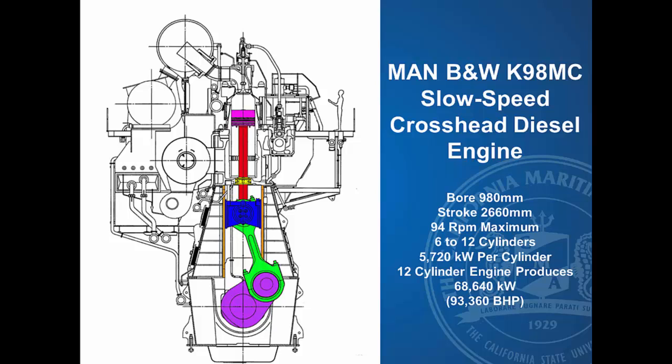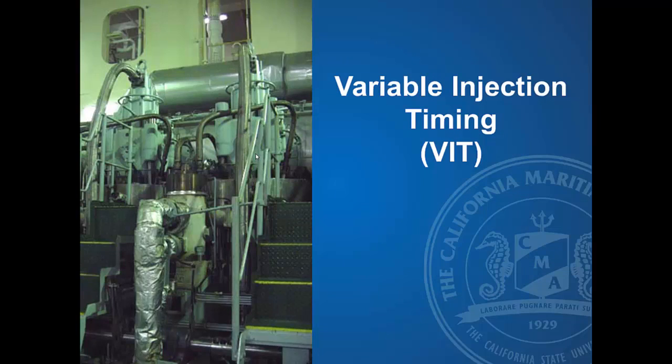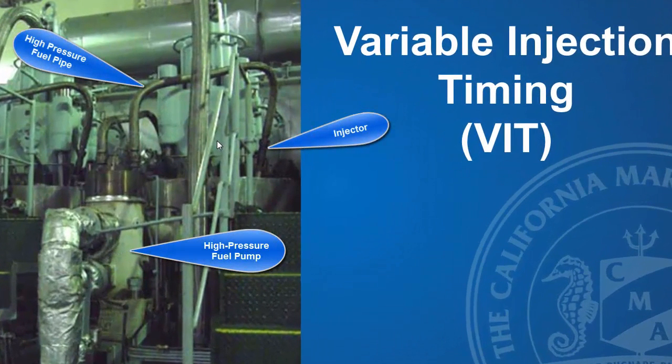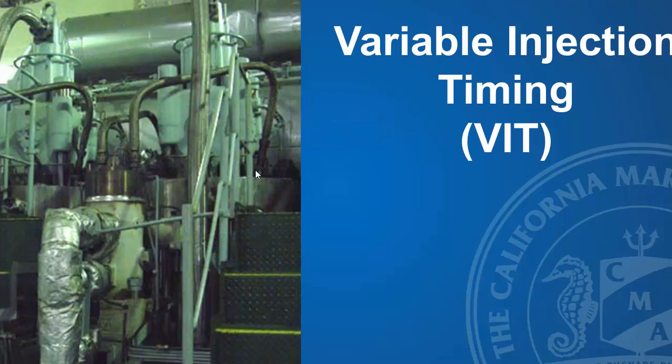And we're going to talk about it in a little bit coming down the line, that instead of a delivery valve, these engines have a suction valve at the top of the chamber formed by the barrel and the plunger. So this is a picture of the Burmeister-Wain high pressure fuel pump, and you can see coming off the top you have two high pressure lines, and the one on the right you can actually see where it comes down, and then you can see the injector itself. And this is the high pressure Burmeister-Wain fuel pump.